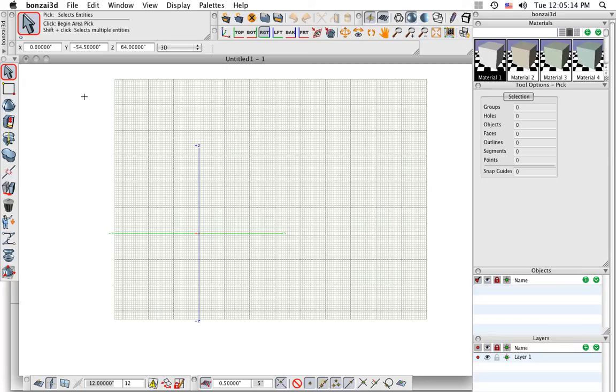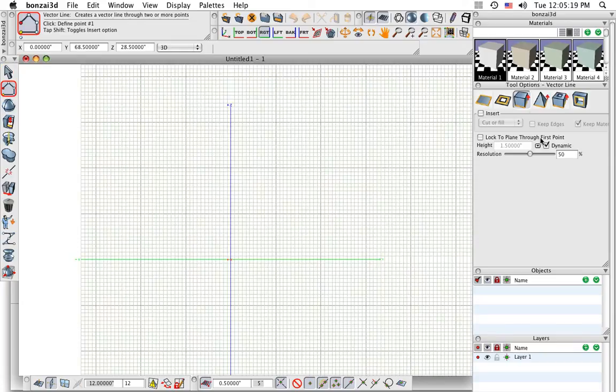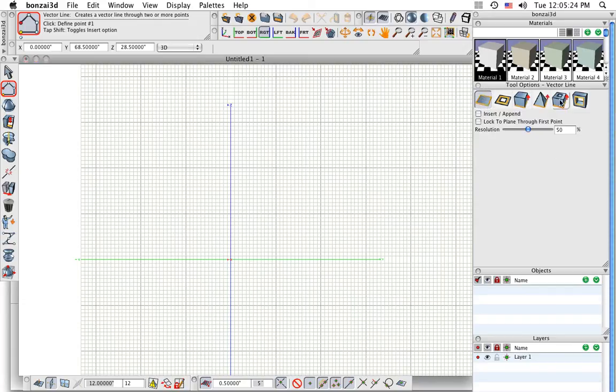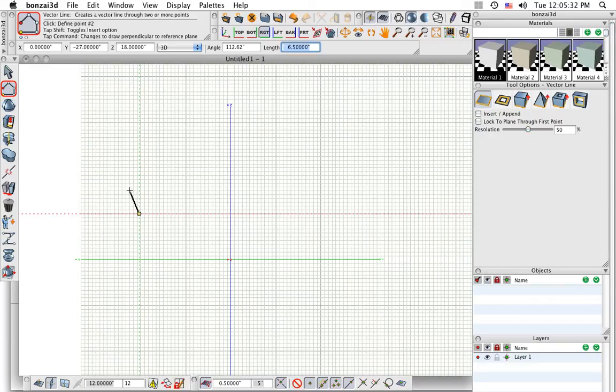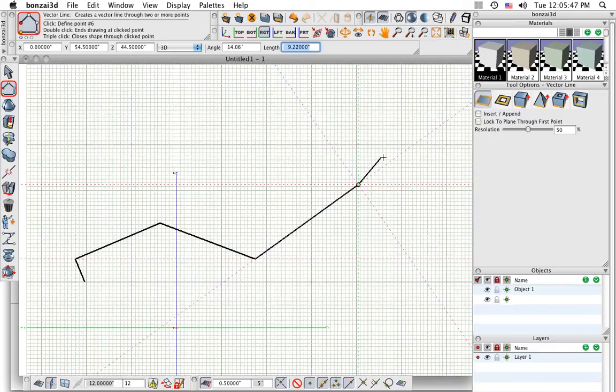So I'll start out by just drawing some basic lines for the frame of that chair. Using the line drawing tool on the left side, I'm choosing the mode that simply draws two-dimensional lines. And we'll use other modes here as the project goes along. Clicking on the screen here and just drawing a few lines. You can see automatically as I'm drawing, I get guidelines coming up that help me line up my points precisely. So I'm doing this as I'm going along. Also pan over a little bit, double click to end.